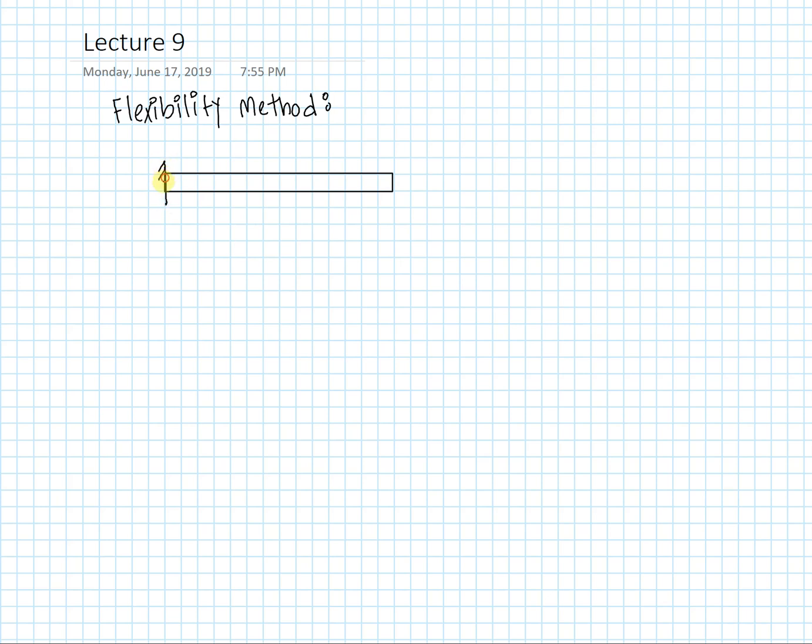And if I were to introduce a truss element again, and this time increase the length of my element by u. So we have this deformation with a magnitude u. I could use a parameter which we called stiffness, k, which we multiplied with the u to give us the force that's necessary to obtain such deformation. And this was p. So for axial elements, we ended up finding that the stiffness is equal to EA over L. That is the elastic modulus, the area of the axial element, and the length of the axial element times u.